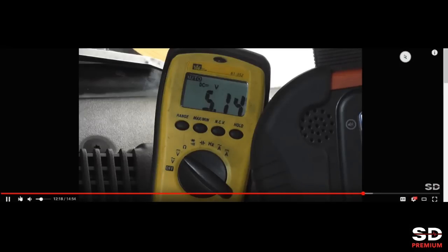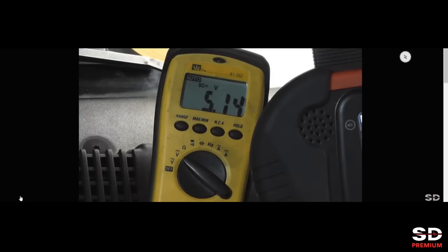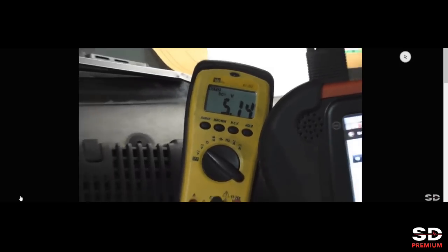It's going to vary on the sensor that you're checking. This is a crank sensor. We should be creating an RPM signal. The computer should react and respond to certain outputs that it would respond to with an RPM signal. One of them is going to be the ASD relay, the fuel pump relay are going to turn on and off because the computer sees RPM. Certain solenoids under the hood may click. In some circumstances, you're going to be able to make the vehicle spark. This particular one needs both cam and crank signals at the same time for spark to take place, so I don't expect the coil to fire. But we're looking for a response. So I'm going to do the test, take a listen to the engine first, and then I'll show you what else we can look at.